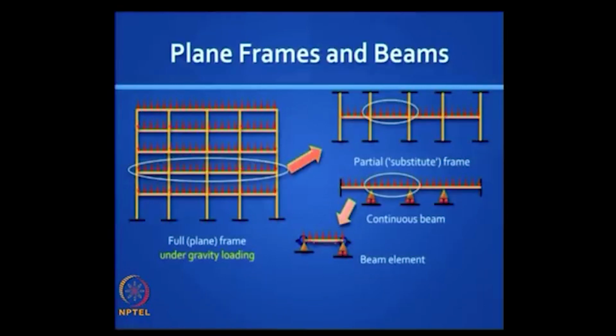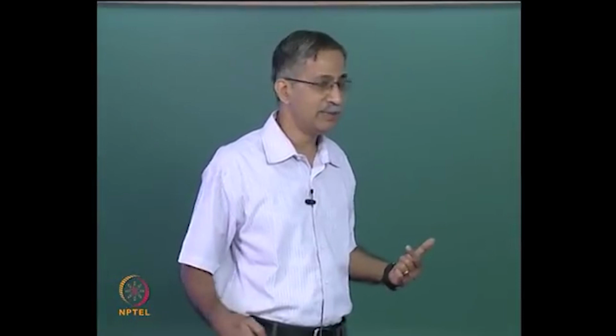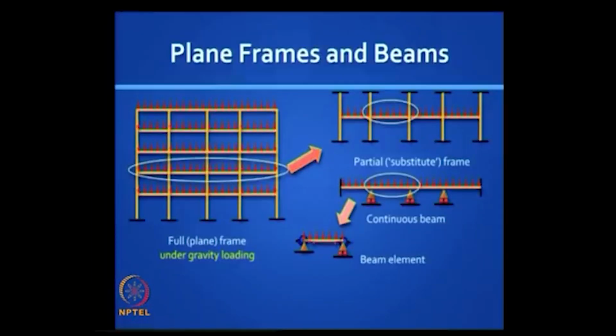But when you take out one beam from that whole big structure, you must recognize that it is not really a simply supported beam, because you get some partial fixity at the two ends, and so it is appropriate to put a rotational spring at the two ends and design for some moment. So this, we know that the bending moment diagram will look like that and the shear force diagram will look like this. The exact numbers are something that you need to find out, but a good guess is good to start off when you do modeling of the beam.